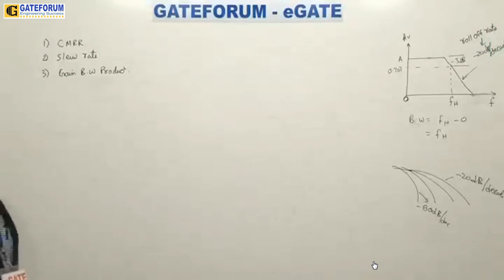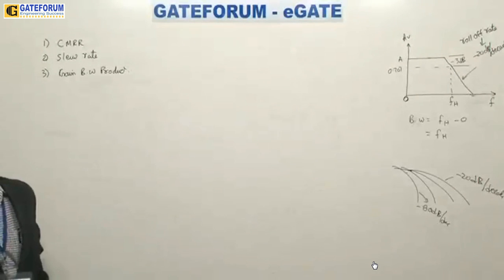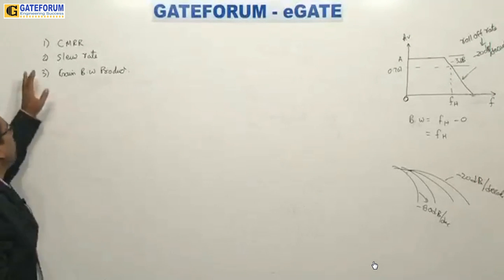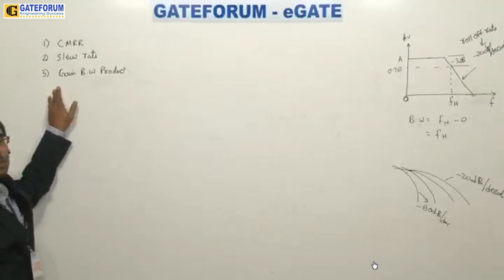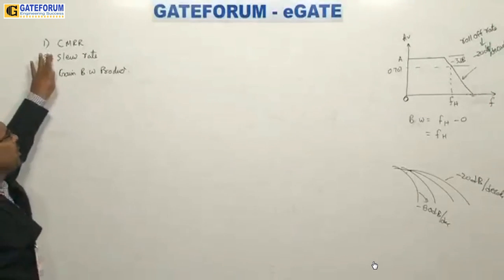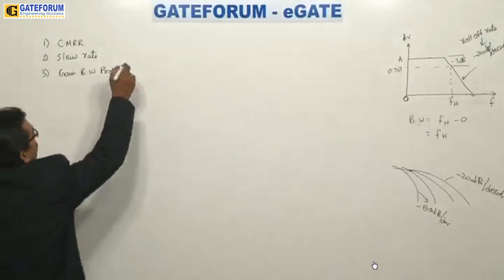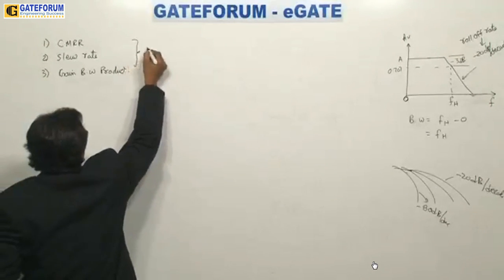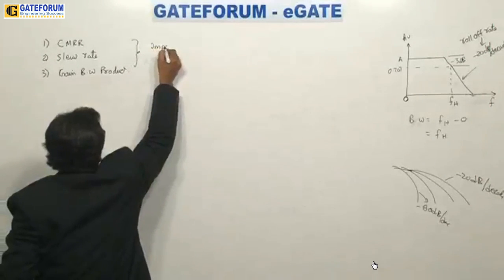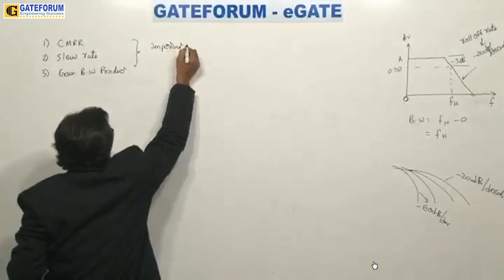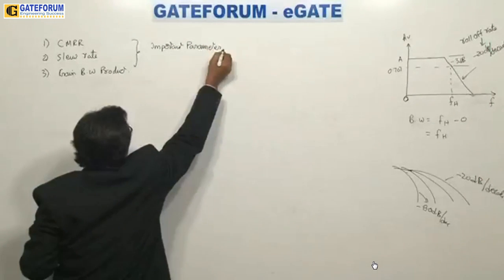These are the most important features of the op-amp. Whenever you select an op-amp, we look at these two factors, CMRR and slew rate, and next we look at the gain bandwidth product. By observing these three important characteristics of the op-amp, we consider whether it is good or not. That is important parameters of op-amp. How do you study that it is a good op-amp or not?